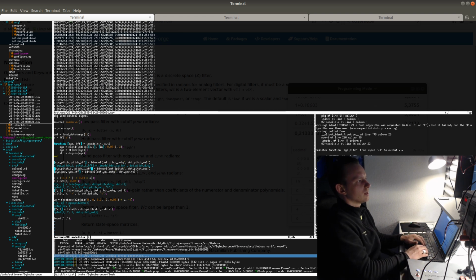Acceleration and current are related, and because I'm going to be getting the acceleration set point, I can use the set point as a feed-forward value for the current controller. But in terms of just getting something here when controlling the duty cycle,